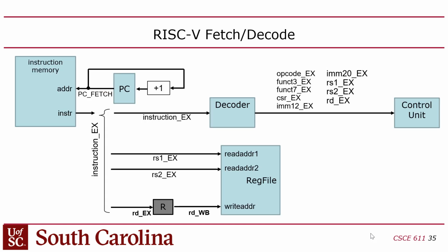Okay, and then the decoder, oh, right, I mentioned this too. It may be helpful for you to create another module that renames these signals with special names instead of just referring to the bit fields in the instruction. Because I can never remember, like, the opcode is bit 6 down to 0. Sometimes I forget because MIPS is 5 down to 0, right? So you can create a decoder that just renames those signals, where you'll have the instruction, and you'll have a signal that will be just assigned with an assign statement from the instruction bits. Does that make sense?